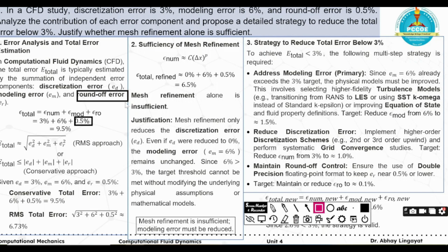So this means from the finite precision of floating point arithmetic in computer hardware at 0.5%, this is relatively low, but accumulated in large scale transient simulation if we use a single precision solver. We have seen the options available there: single precision or double precision.